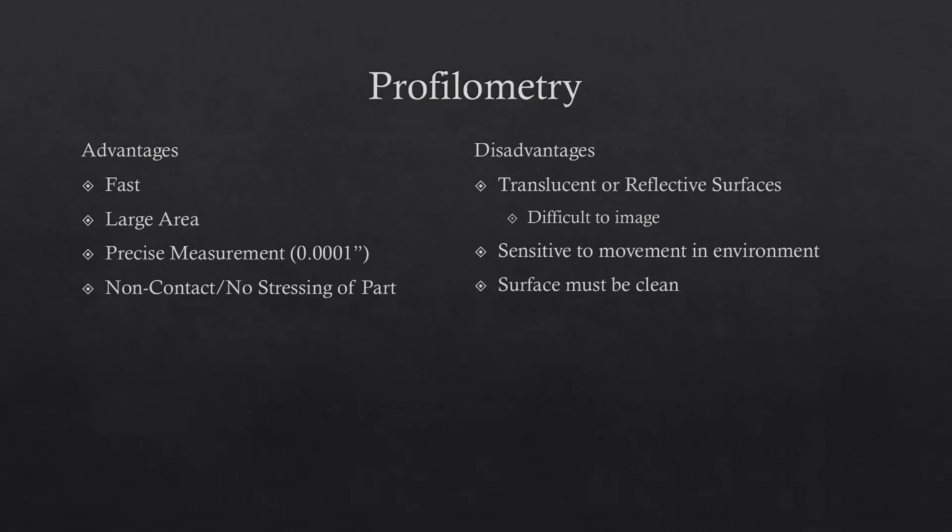And so we would use a profilometer to scan the nose of the airplane, between the radome and the windshield. That was usually the area that got it the worst. Essentially it would create a topographical map of that part of the airplane. We could then send that profilometry data to the aircraft manufacturer's engineering department.